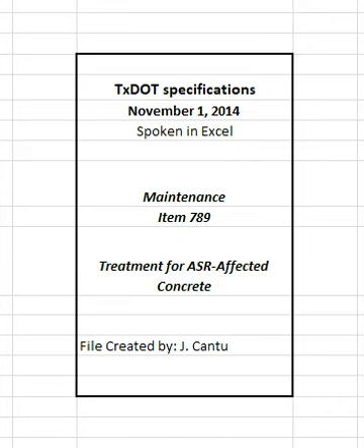Use a trowel, spatula, or similar device to effectively work the caulk into the crack and provide a smooth profile to the bead of caulk. Ensure the caulk does not completely fill the crack, but completely covers the crack opening. Remove any caulk remaining on the surface of the concrete using the trowel or spatula before the caulk has set up. 4.4 Application of topcoat.